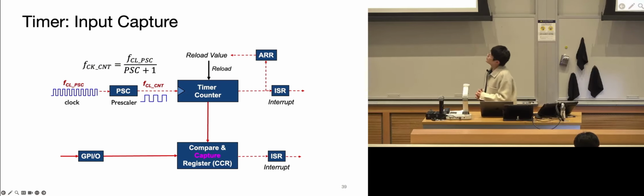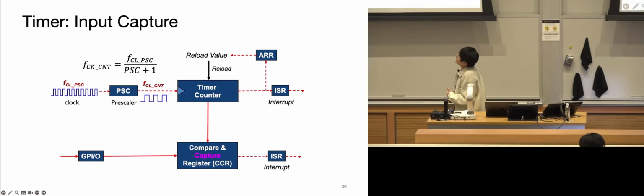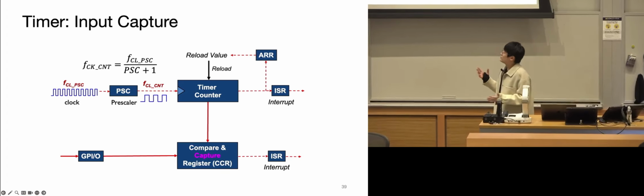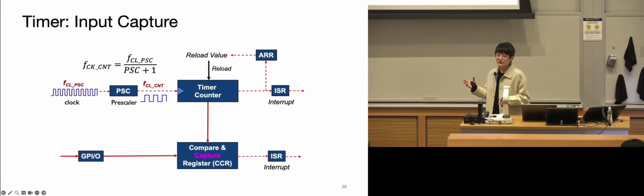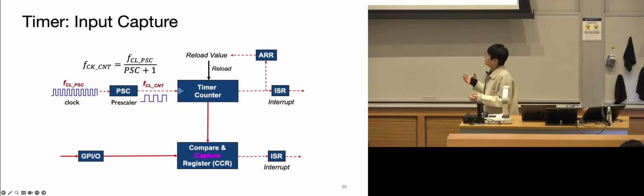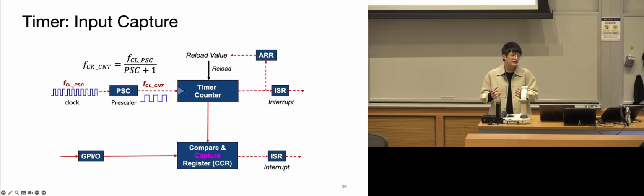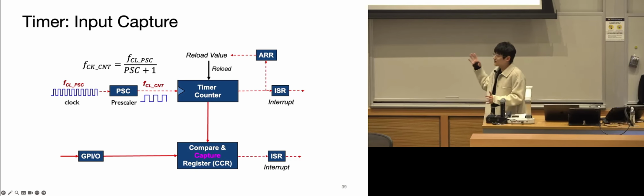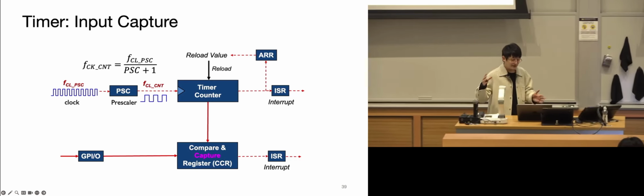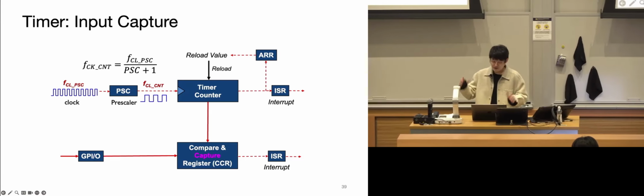One thing to notice when you do the calculation, make sure you remember to add 1 to the prescaler. Whatever prescaler value you set, you will add 1 and then use that to divide the clock. That's a system protection so that no divide by 0 will occur during any type of configuration. So it's possible that your prescaler value ends with a 9 or a 99 or whatsoever.